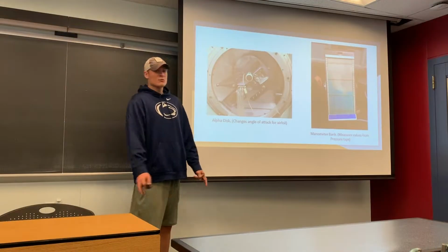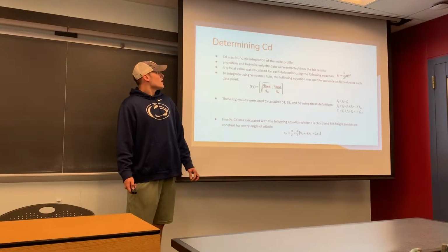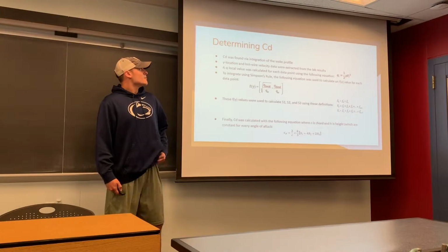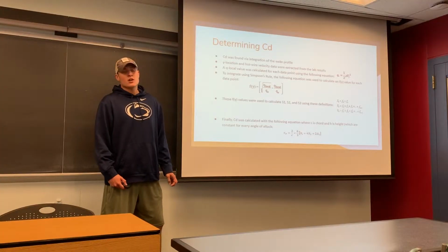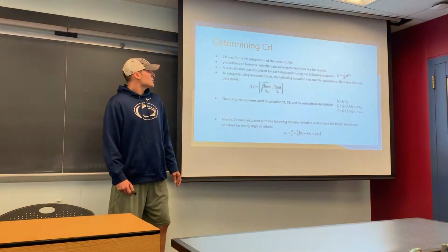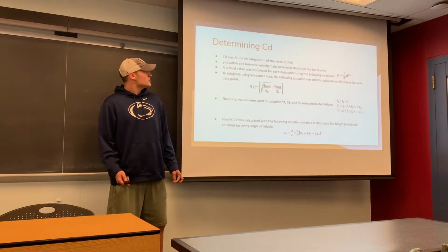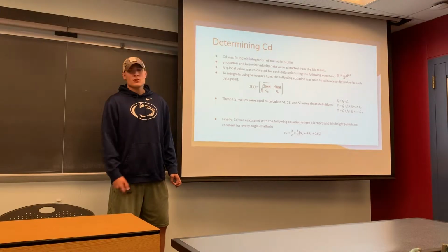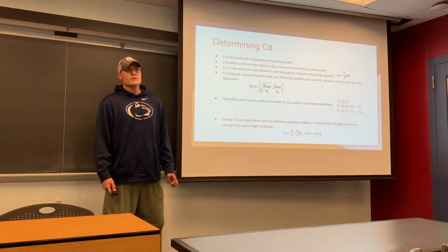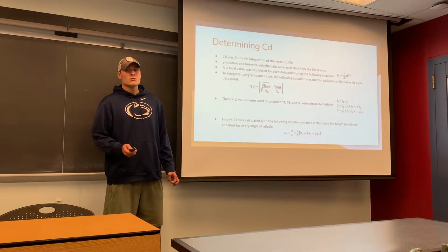Hi, my name is Zach Rollman. So to determine CD, our method was integrating the wake profile using Simpson's rule. So first we extracted the Y location and hot wire velocity data from our lab results. And a local dynamic pressure value was found for each data point using the q equals 1/2 rho V squared equation. And then to integrate, like I said, using Simpson's rule, those q local points were plugged